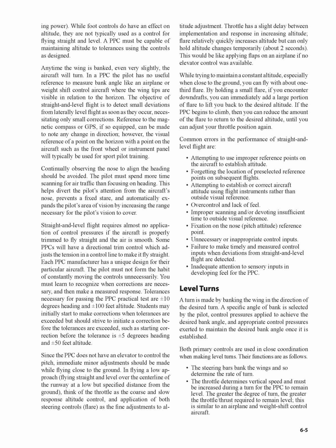Straight and level flight requires almost no application of control pressures if the aircraft is properly trimmed to fly straight and the air is smooth. Some PPCs will have a directional trim control which adjusts the tension in a control line to make it fly straight. Each PPC manufacturer has a unique design for their particular aircraft. The pilot must not form the habit of constantly moving the controls unnecessarily. You must learn to recognize when corrections are necessary, and then make a measured response.